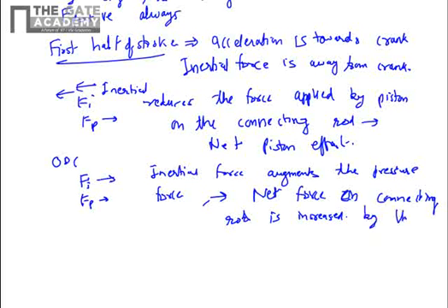So the magnitude is same, but the direction changes with the crank angle, and towards the inner dead center it opposes the pressure force from gas, and towards the outer dead center it augments or aids in the same direction as the gas pressure force.